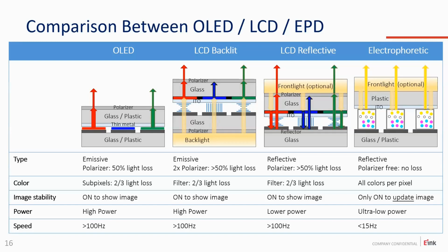LCD, it is kind of similar in that it is emissive, but also very different in the stack. And those are also the advantages of OLED, of course. OLED is thinner because it doesn't need a backlight. It only needs one polarizer.